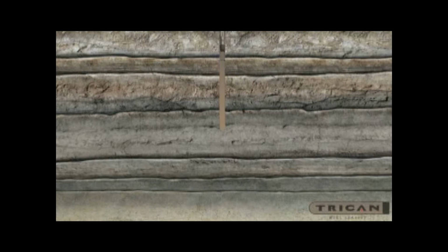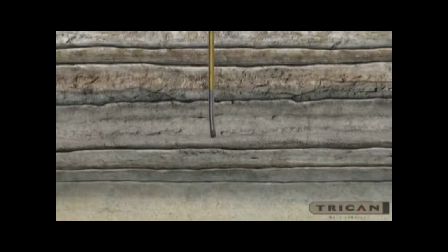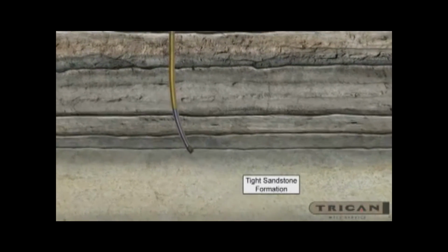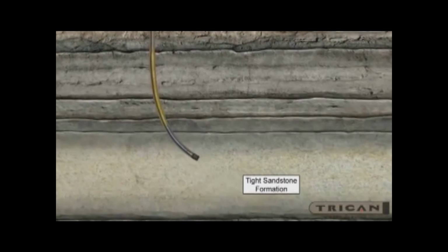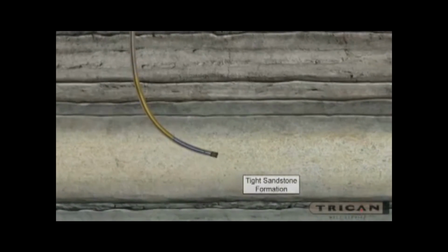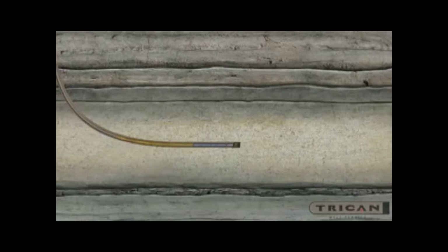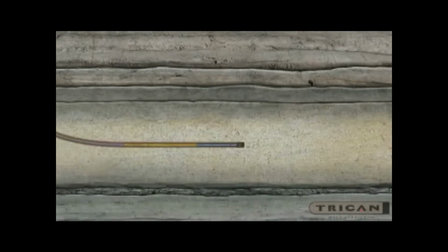Again, the pipe and bit are pulled out of the hole, and a downhole drilling motor with measurement while drilling instruments is lowered back into the hole to begin the angle building process. The distance to make the curve from the kickoff point to where the wellbore becomes horizontal is just under 1/4 mile. Once the curve is completed, drilling begins on the well's horizontal section, called the lateral.